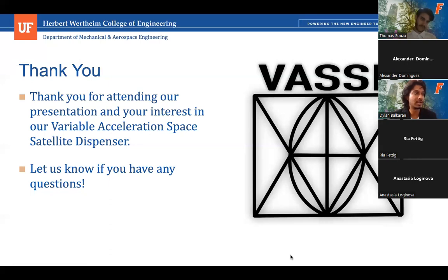We would do design iterations where we took the gusset and made it way overbuilt, and then we would do hand calcs to verify critical locations, similar to what Carlos was showing in his analysis, because that diagonal portion had most of the concentrated load. So that was just a hand calc to verify our FEM. And we did that from a design iteration standpoint to see how much we can shave off in weight while still being able to withstand that load.